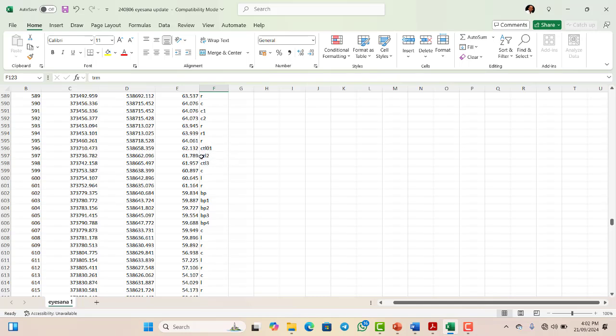So without this control, sometimes it might be difficult for you to set out the road alignment. So it is very important that as a highway engineer, when you are asking a surveyor to go and survey a road for you, you need to tell him that he has to establish temporary benchmarks, or what we also call control. Okay, so you can import this to Civil 3D directly, or you can use this CSV.